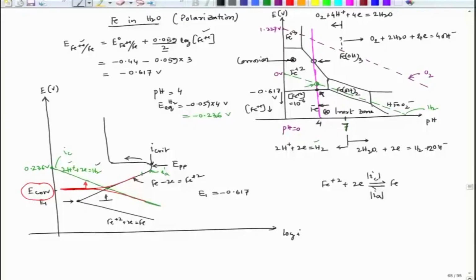So, the corrosion rate or the dissolution rate or the I_a should reduce, and that is what happens rapidly, and then it appears as I_p, because this I_p corresponds to the dissolution rate as decided by the solubility product of Fe(OH)3, or the other way around, the ion movement from the metal surface to the electrolyte.